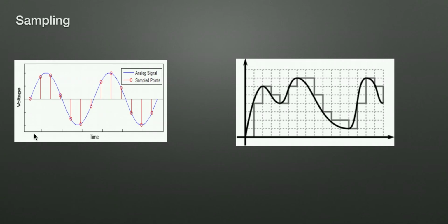If it is a continuous signal, you would definitely have infinite intensities of voltages present between this point and this point, and the computer cannot store that much. So the only solution that comes up is sampling the time. In this, you sample the time. You take only those points of time where you actually want the particular intensity value, and then store that.